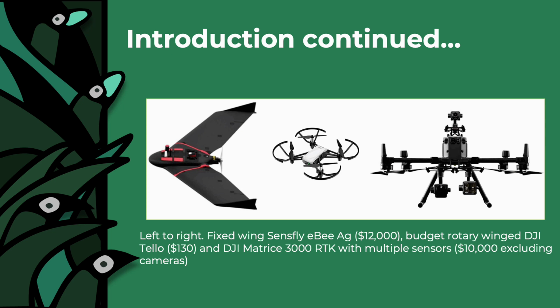Most consumer-grade UAVs are equipped with GNSS or GPS, capable of plus or minus 2 to 5 meters accuracy, and with a barometric altimeter that can be affected by varying atmospheric pressure and elevation, both of which introduce imprecision into the output from mapping flights. While this level of accuracy might be sufficient in some instances, such as generating maps for planning purposes, if the UAV mapping output is to be integrated with other georeferenced data as part of an investigation for unmarked graves, this level of imprecision might be problematic.